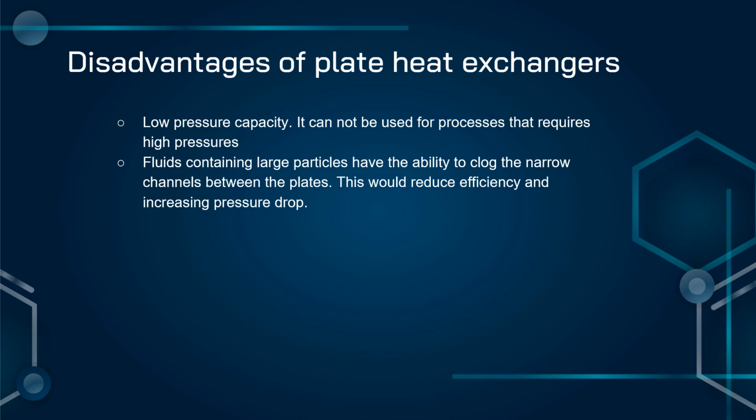Another disadvantage is that fluids containing large particles have the ability to clog the narrow channels between the plates. This would reduce efficiency and increase pressure drop.